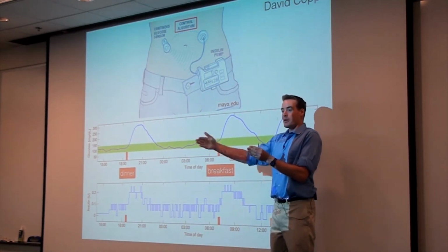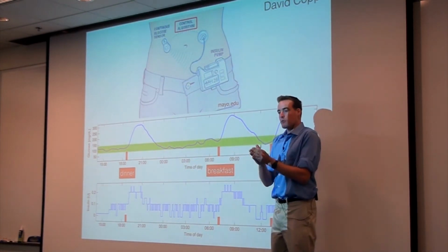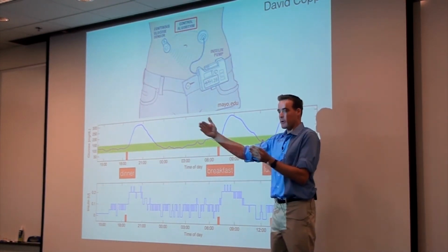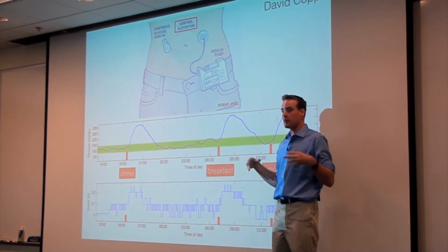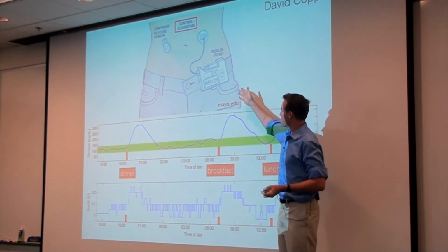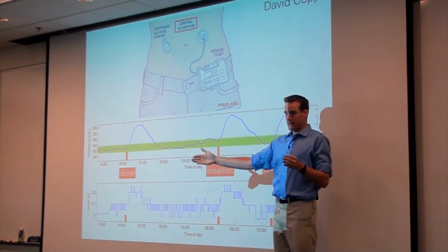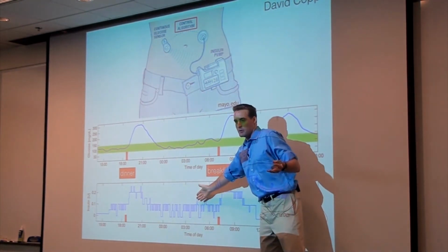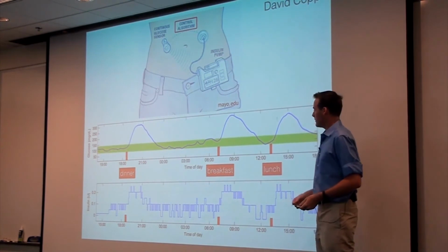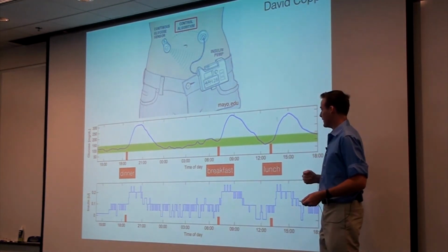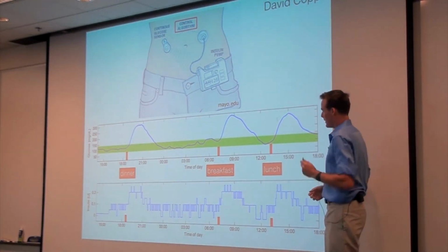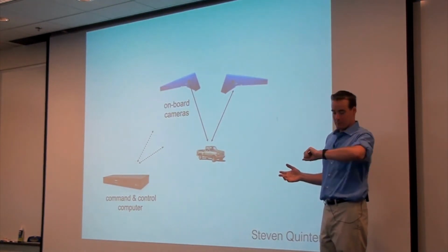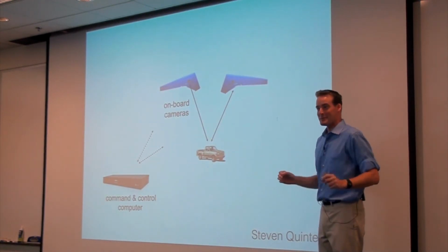So the remaining 40 minutes of that plan, it then discards, and it recomputes the entire optimization another 45 minutes into the future. So this is a technique called model predictive control, because he's using the model of the human body to predict what the blood glucose level will do as a function of some sort of optimal insulin trajectory. Anyway, so that's what David does, and I think that's very cool. Okay, here's the last example, and then we're done with time to spare.